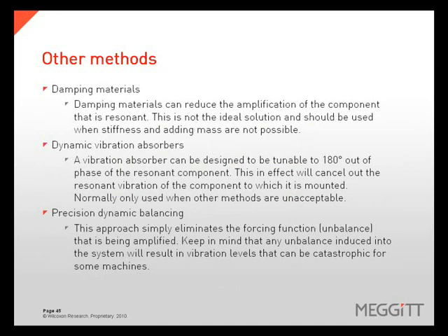Other methods that can be used to address resonance issues include damping materials, dynamic vibration absorbers, and precision dynamic balancing. These methods are not really correcting the resonance problem, but rather minimizing its effects, and are usually only used when changing the stiffness or the mass is not practical.